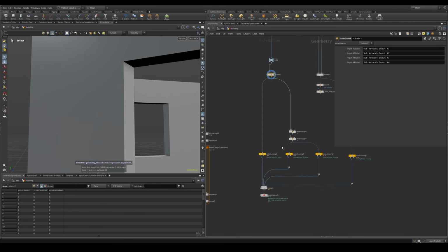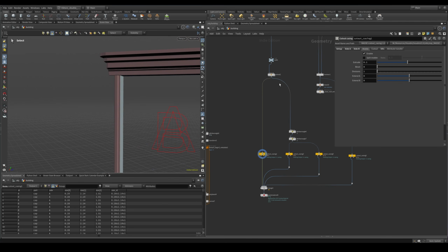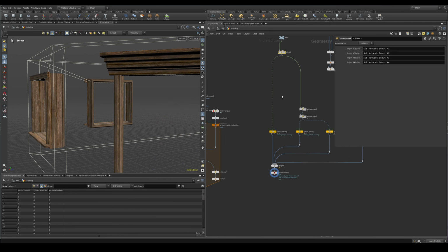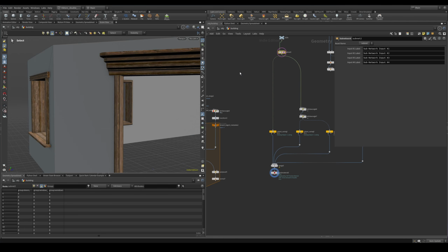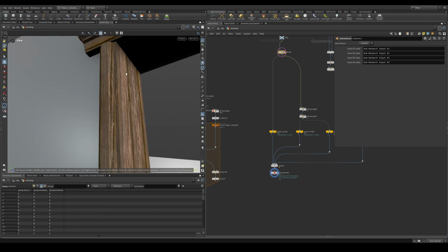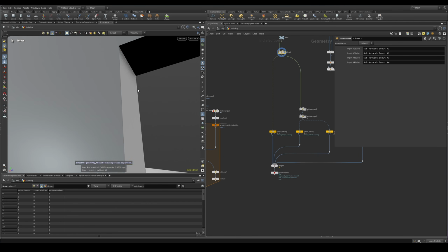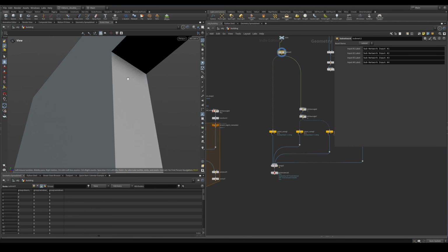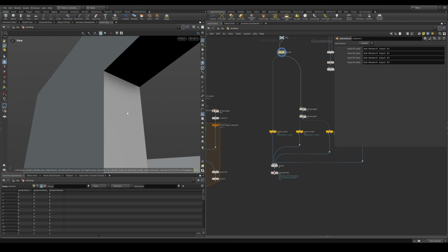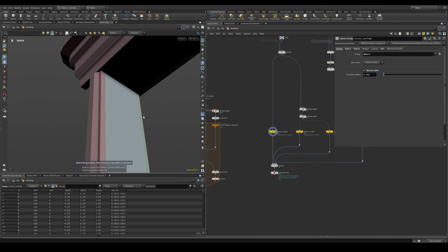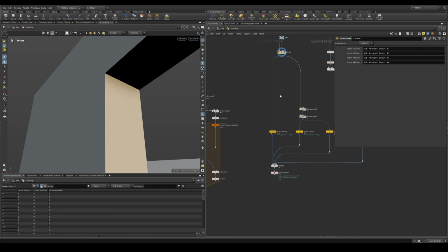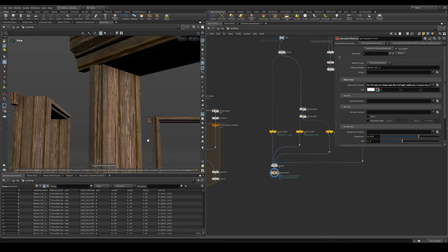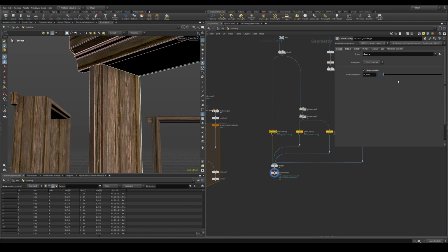And internally, the HDA is going to do a little bit of a value adjustment. So the value adjustments are controlled by this precision offset. It's just set to a very small amount. So this is done to prevent any Z fighting between the casing and the source polygons that we use to create the casing. Because if our middle part of the casing would be at the same location as this one, we would have ugly intersections. So this is where the precision offset comes in very handy.